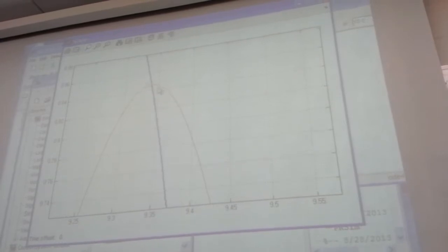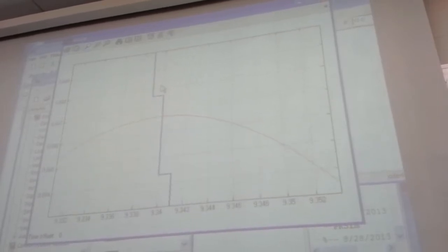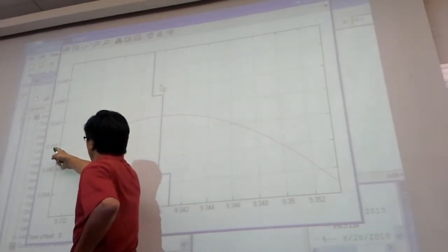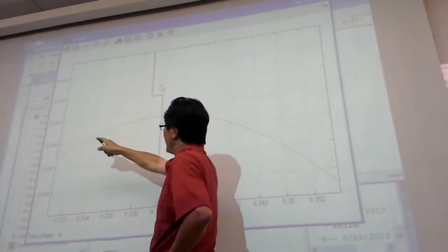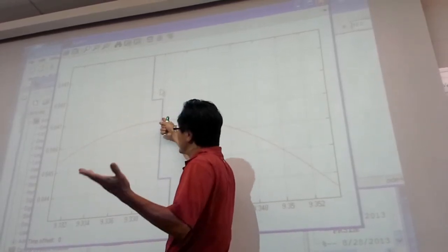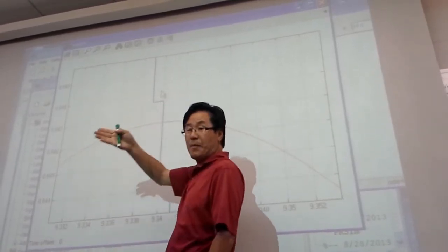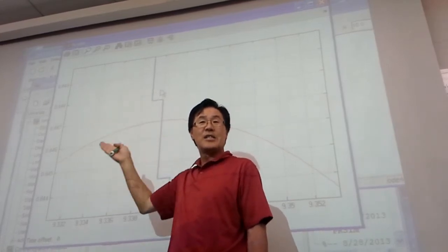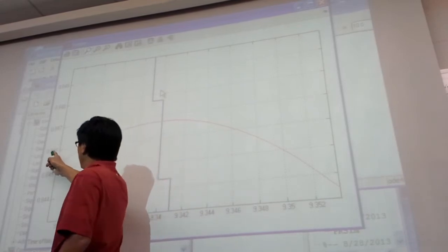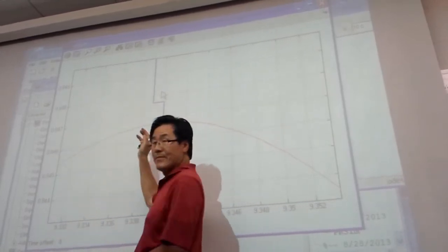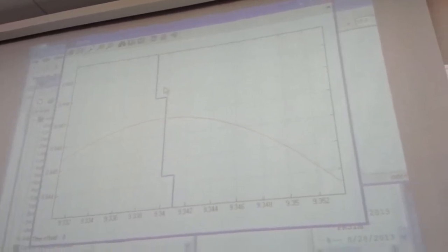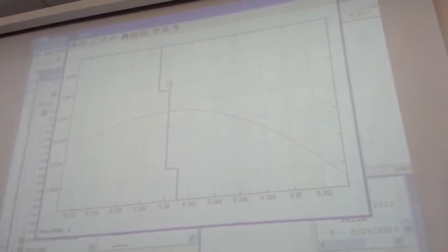So your gain will be about 0.8467 divided by 1. So this system has gain 0.8467. Now you have to make sure, and I'd like to point this out clearly, that my transfer function is 1/(0.1s+1) here.